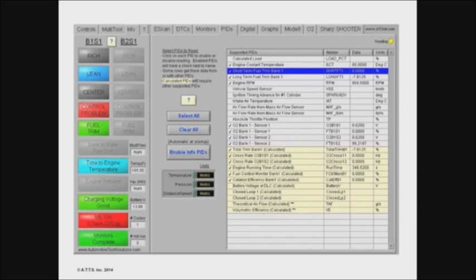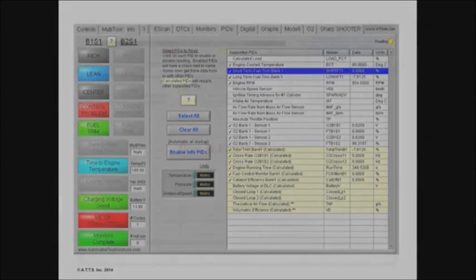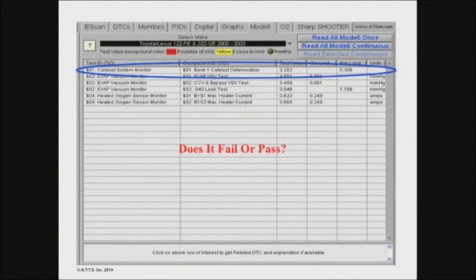So now this one actually passed. Look at the limits. They're tight. 0.253 test value, max 0.30. Not a big one like you've seen from Toyota before, 0.998. Each different car line or computer, they could change stuff.